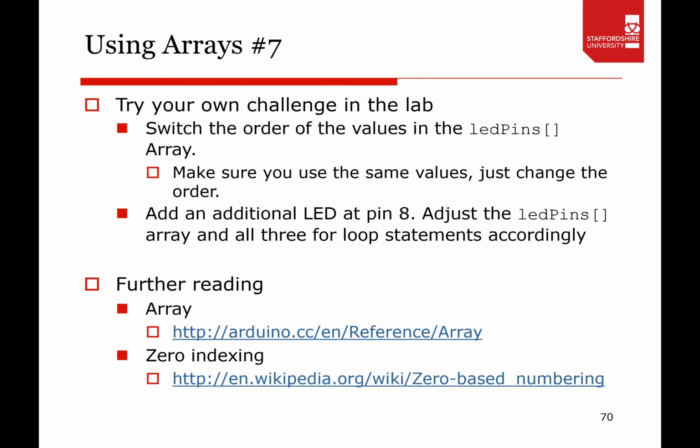So try your own challenge in the lab. Switch the order of the values in the LED pins array. Make sure you use the same values, just change the order. Add another LED at pin 8 and adjust the LED pins. And then you've got some further reading.